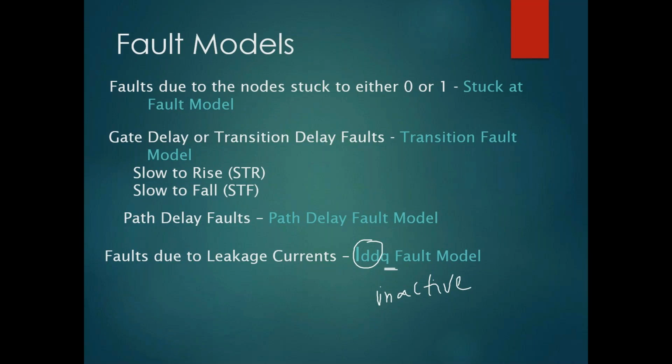So how do we test it in DFT? Can we test the current in the DFT? 100% no, but we can help some other team by producing some vectors. We are going to produce some vectors and give them to another team, called the IR analysis team. The IR analysis team, taking your output as input, can check where the hotspots in the design are when the device is almost in an inactive state.